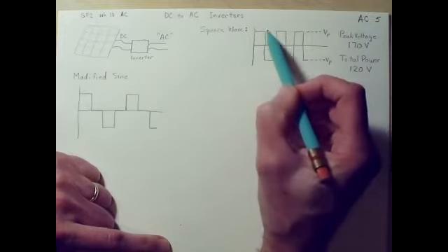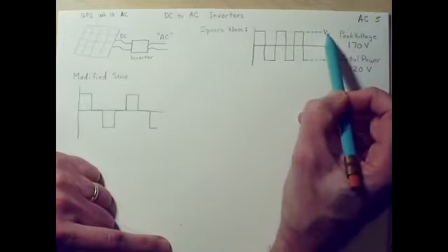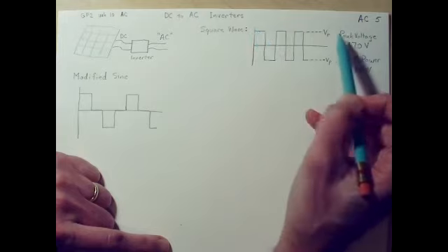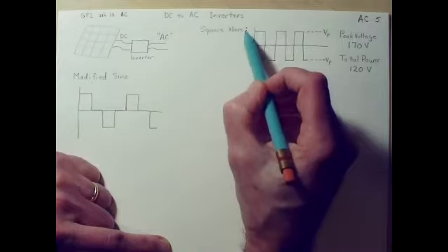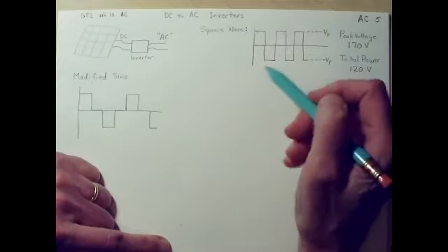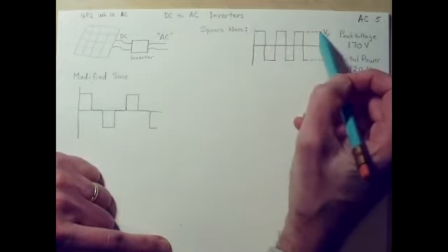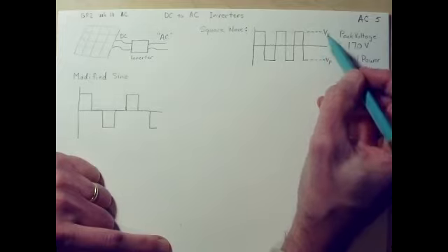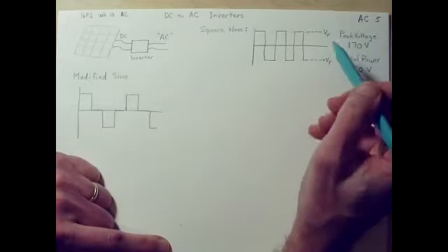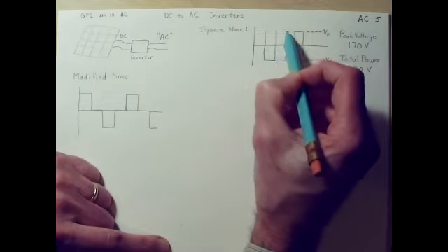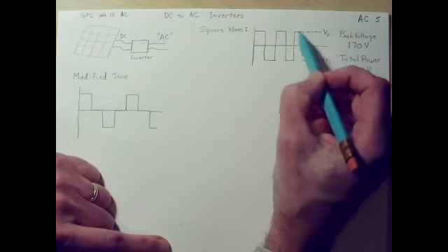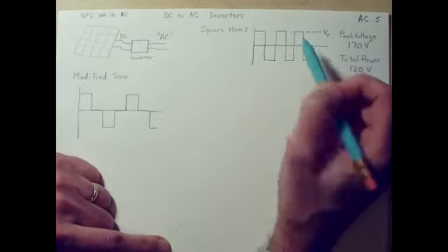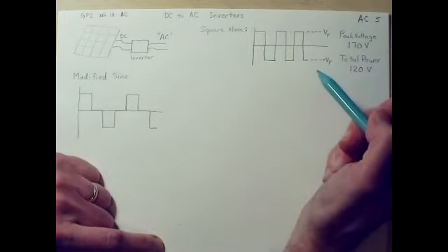So you're going to get the same constant value of VP squared when you square this. Then when you take the average, well, the average of something that's constant is just whatever that value is. So it's just VP squared still. And then you take the square root, and that gets you back to VP. And so the RMS value of this is just the same as the peak value. There's no difference between those two.